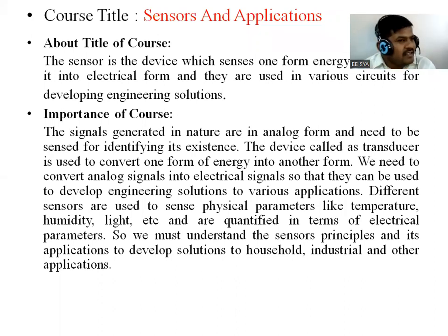Suppose the output of that sensor is in the form of voltage, and you set that value of voltage, meaning we are controlling using a sensor, for example a tank, whether the tank is full or not can be sensed by that sensor. At that situation, we give a reference term to the circuitry, right? Beyond that value, the sensor senses that the tank is full and the valve will be closed. So it will give a command to the controlling circuitry, right?